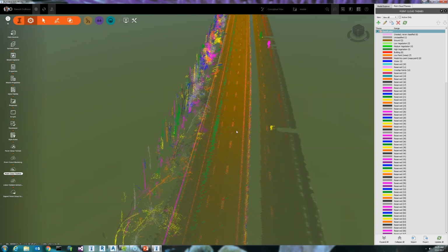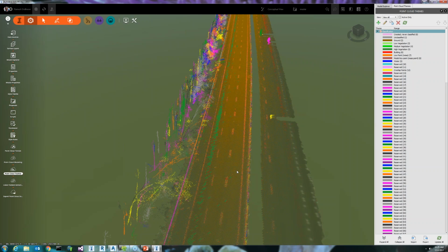So at this point of time, this is step one: how to prep the data, how to create a terrain, how to classify the point cloud, and get what you want so that you can do the feature extraction very efficiently. Very simple. Now I'm going to go to the linear feature part, the second step. Any questions right now, Eric, before I move on to the next one? One just popped up. It says to use classification, the classification must exist in the original source data, correct?